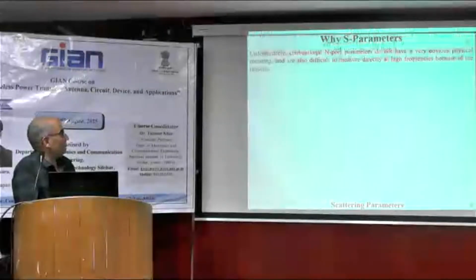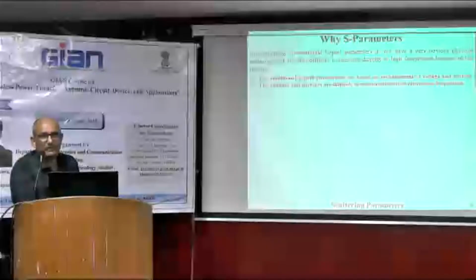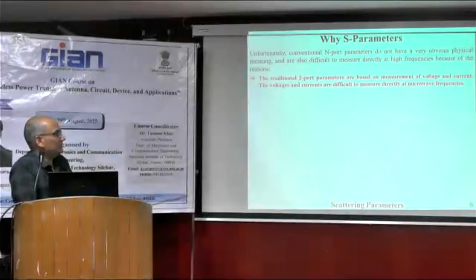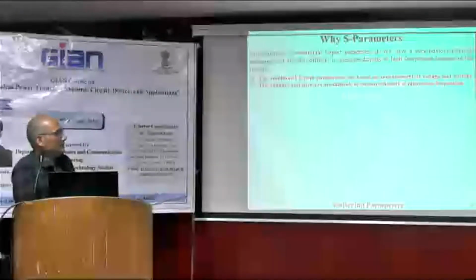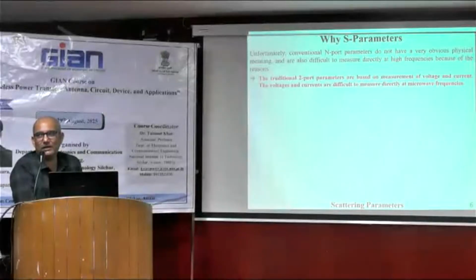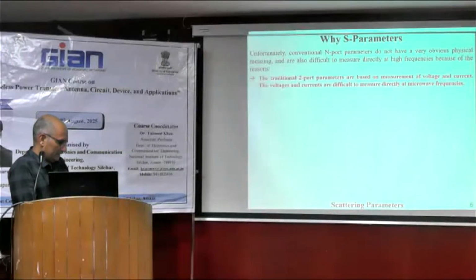What is the first reason? Traditional two-port parameters are based on measurement of voltage and current, but in high frequency we always play with power, incident power or reflected power. Voltage and current are difficult to measure directly at microwave frequencies. A power meter will be there at high frequency, but generally we don't prefer to have the measurement facility for high voltage and current measurement at high frequencies. That is the first reason.